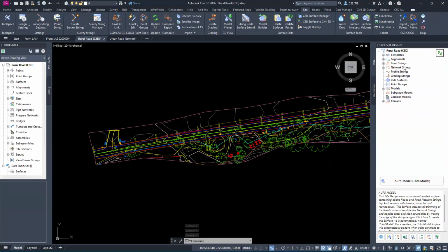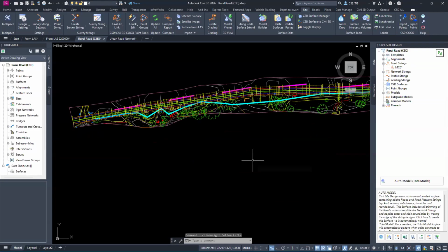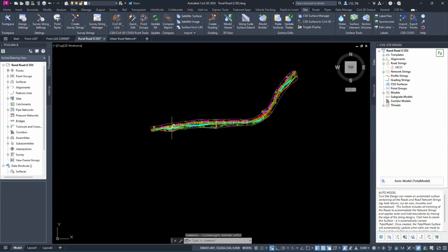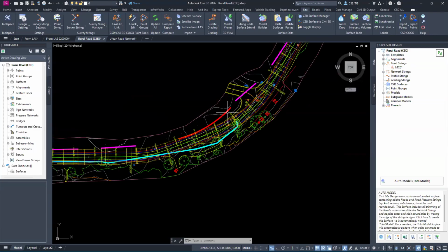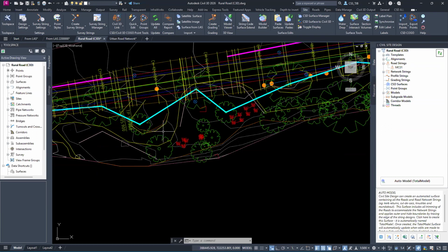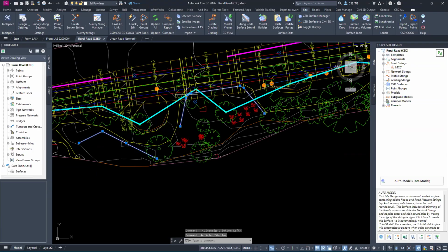To see my string sampling locations, I click on the string in the tool space here and I toggle on off the section lines and I can see all the sample spots. Now to highlight where I've actually put in things, I did set up the layers to be line weighted. So all the pink ones are all my lines. The red one here is my arc. The blue one is my polylines. And the white ones, which I can't make thick, so it's these ones, are my 3D polylines. And if you actually look, you can see all the vertices of those things are being tracked as sample points inside my model.